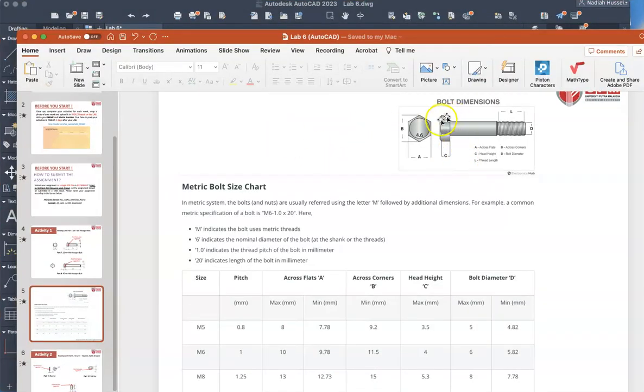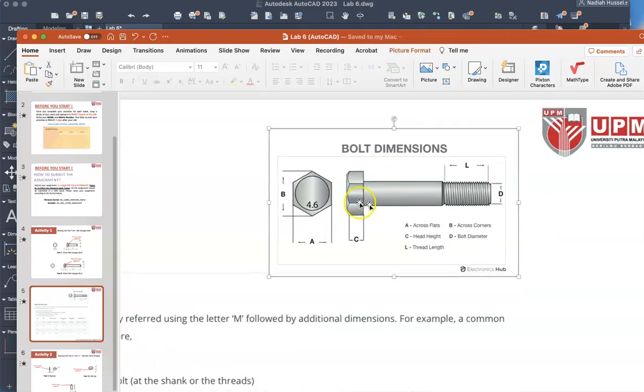So now we have these things, but it did not specify what the dimensions of these things are. Okay, so if I were to try to figure this out, I can see that it is somewhat aligned to this flat side. Do you see it? So we are going to follow that, then make an arc for this. And you can see over here we have some sort of a chamfer. It's not a fillet, it's a chamfer because it is very sharp.